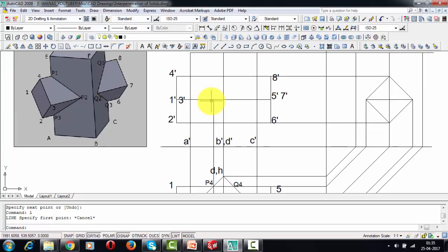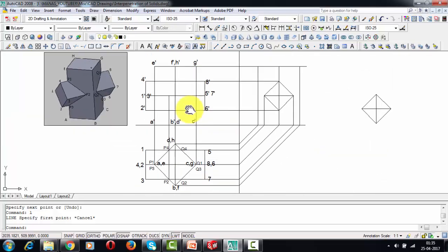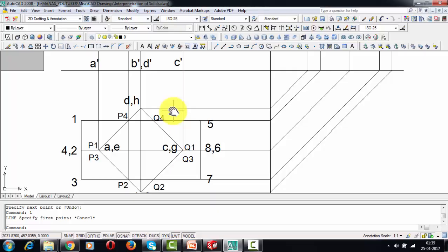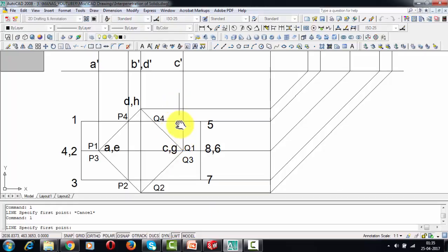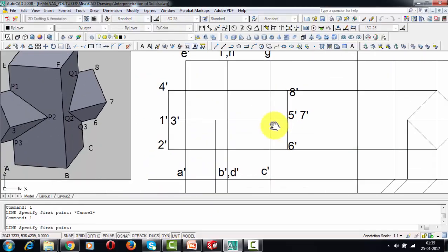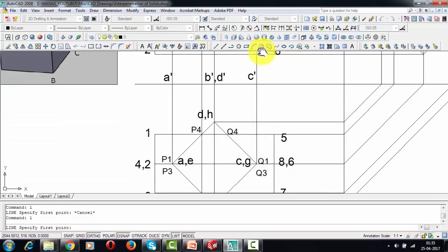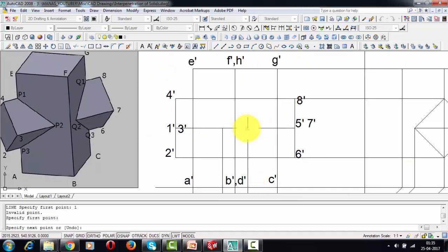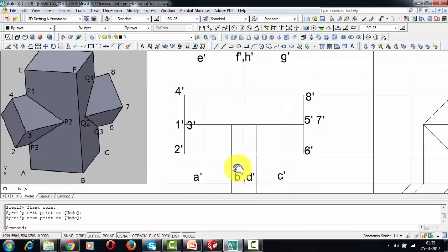That is going to be P4. Similarly over to this side you're going to have more piercing points like this. So this is going to be point Q2, and behind Q2 you have Q4. So this is going to be Q2 dash comma Q4 dash. Similarly, let us have one more piercing point. Let me extend this further. So here for Q2, please watch this carefully. Here there is Q2, and behind Q2 there is one more piercing point, that is Q4.